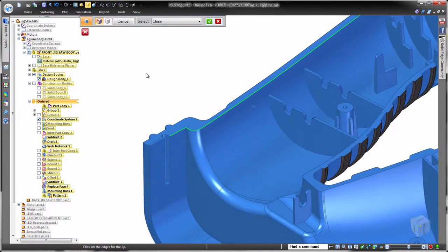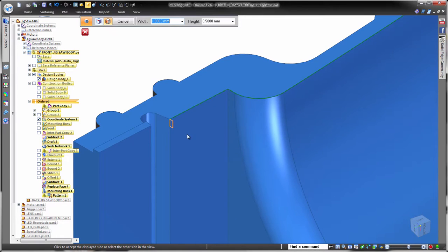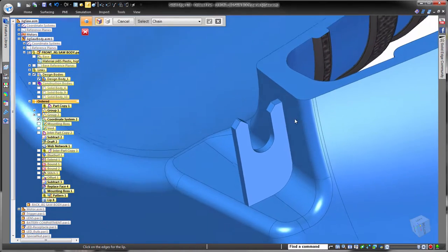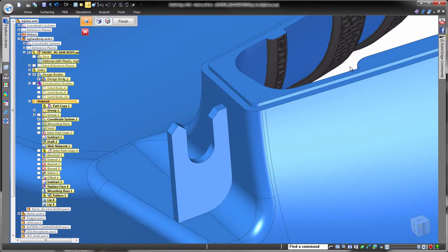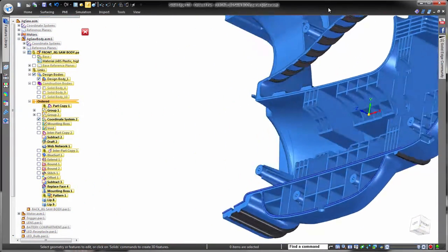Here we'll add a lip feature to the inside edge along the top of the housing. Notice that as we simply move our cursor around, we can change the location of the profile and therefore specify creating the lip above the edge. As we pan to the center of the handle area, we'll generate the same dimensional profile, yet by simply adjusting the location of the profile into the part, we can quickly generate the complementary groove below the edge.